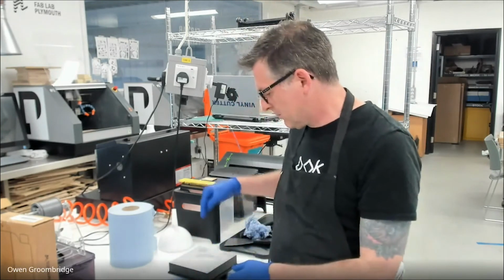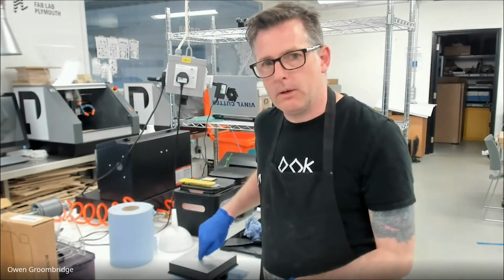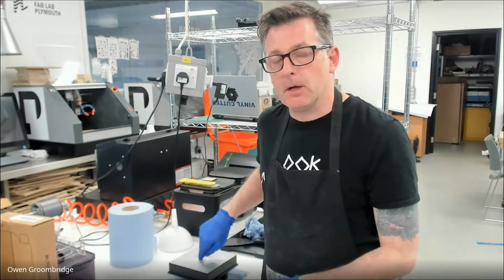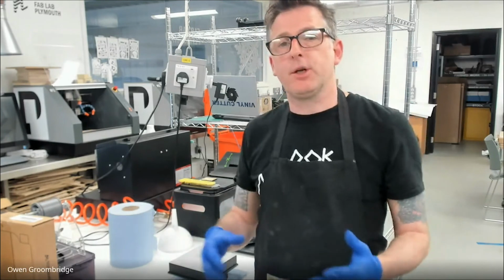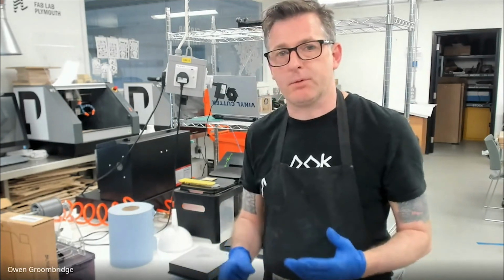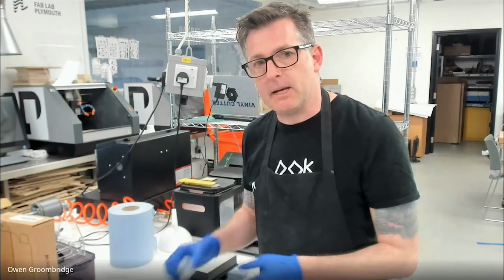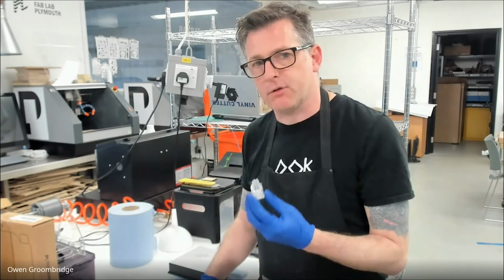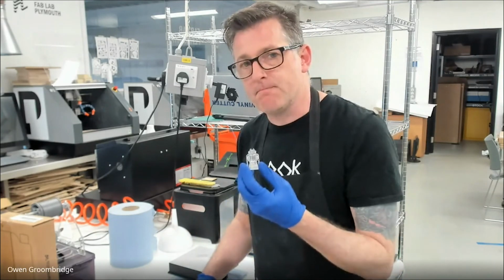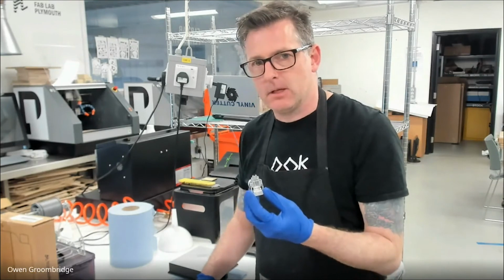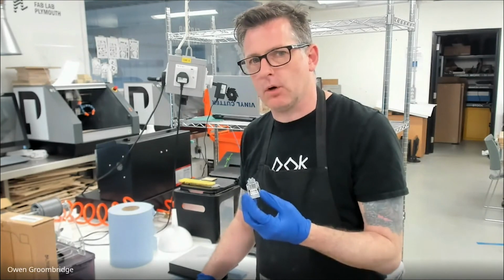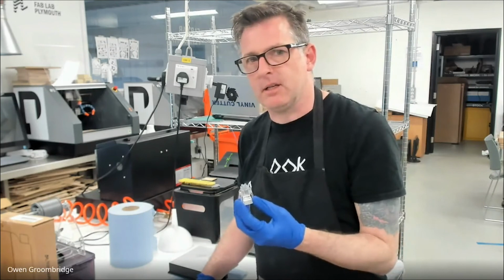As soon as it comes out of the cleaning tank, as soon as it's come off the bed here, we put it in a dark cupboard. The reason is that if we cure it, it changes the composition of the material, and it means that when it's cast in plaster of Paris or whatever, it doesn't burn out cleanly. That's not good if you're casting 18 karat gold into something.